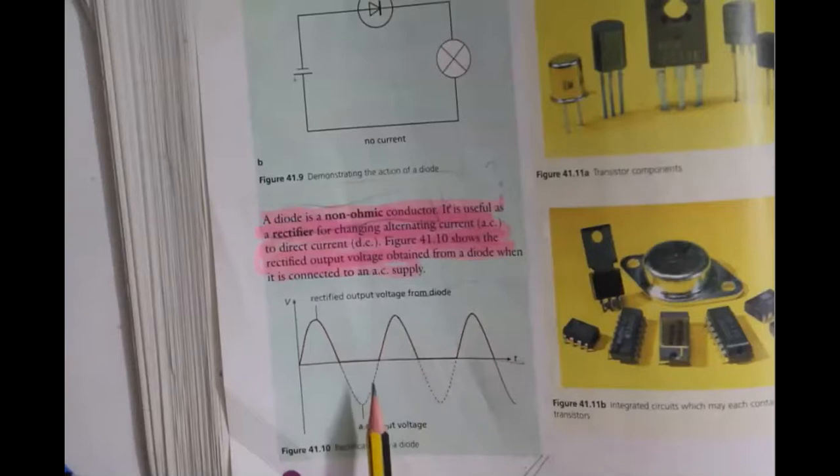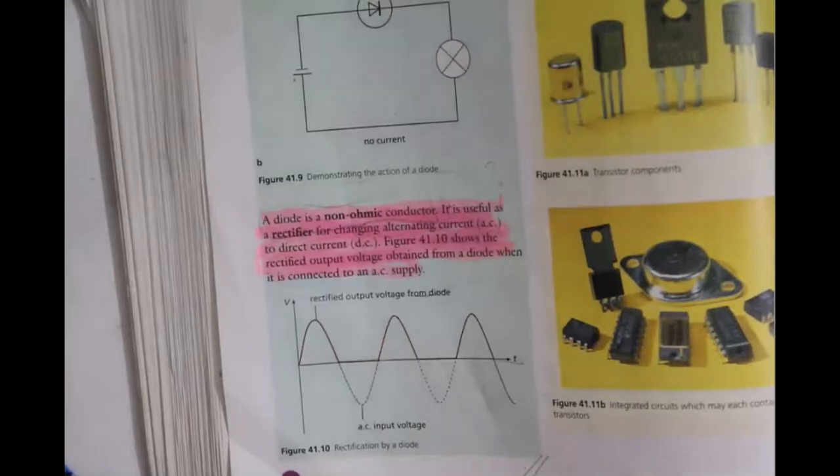Yeah. And so the horizontal axis is representing time. And so direct current will be when you hide the reversed direction, I mean, the negative part. That's why they have made the negative part dotted. They mean to say that the negative flow of the current is eliminated by the diode. But if it was there, the graph would have looked like this. But because the reverse direction of the current has been rectified by the diode, they are representing it with dots.